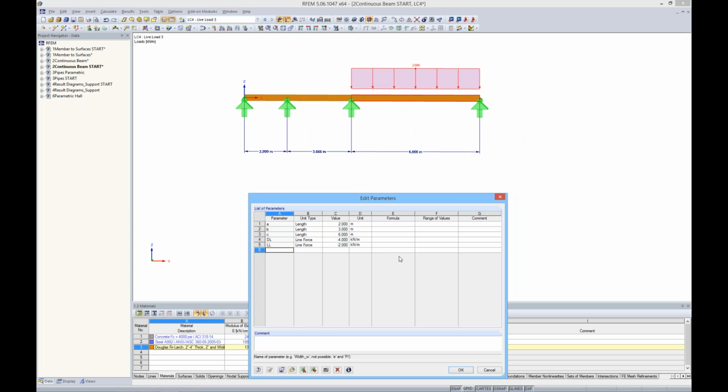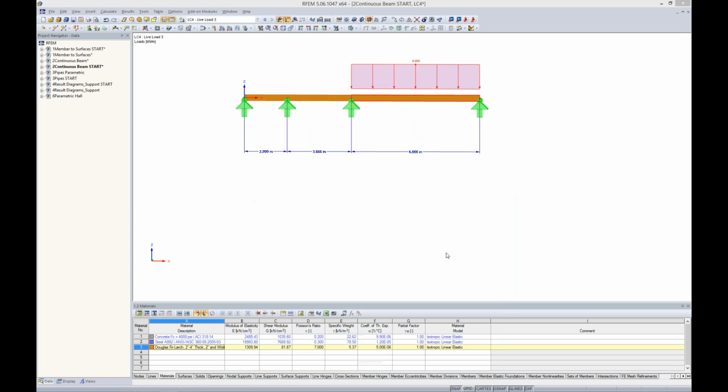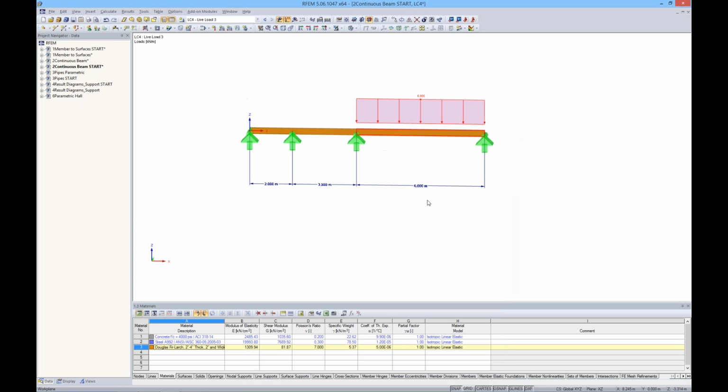We should see that everything is updated just fine. For our live load, we'll go ahead and choose -6 and apply that, and everything is updated. So you can see that this is obviously quite valuable, again, for a lot of the similar structures that you're working on, or maybe it's the same structure and there's a lot of changes going on within the design process. So that sums up that simple model.